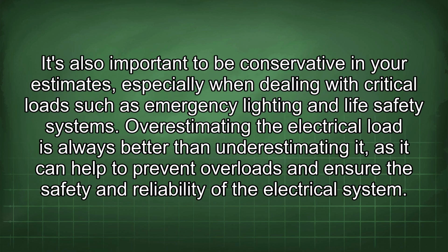It's also important to be conservative in your estimates, especially when dealing with critical loads such as emergency lighting and life safety systems. Overestimating the electrical load is always better than underestimating it, as it can help to prevent overloads and ensure the safety and reliability of the electrical system.